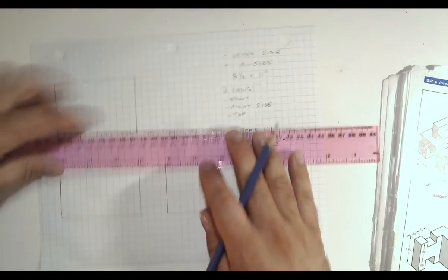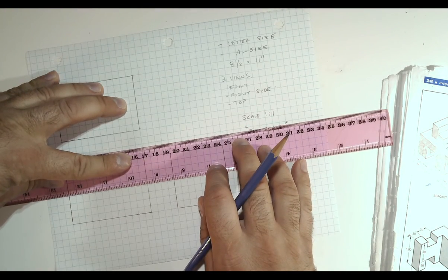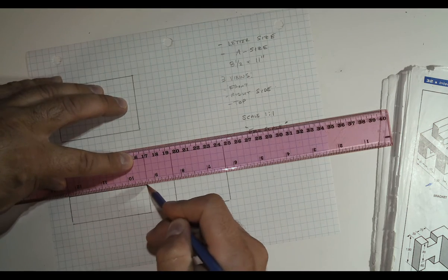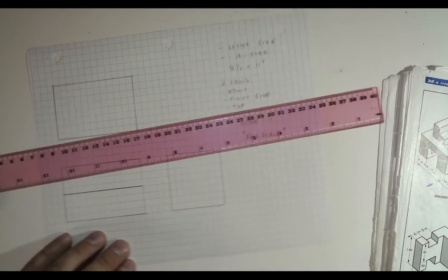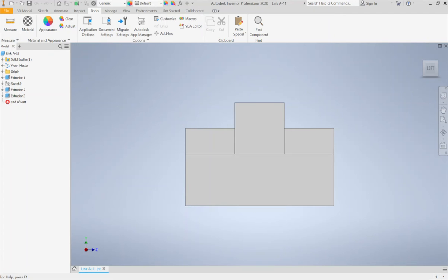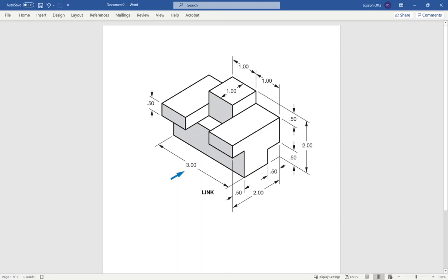So there is a surface here that is 1 inch in height, and I'll capture that, and you're going to have to read the drawing to determine that this is 1 inch in height. And how I do that is simply looking at the actual drawing, taking the overall height, the 2 inches, and we're just going to subtract away this 1/2 inch thickness, and there's another 1/2 inch thickness here, right, as specified by this dimension.